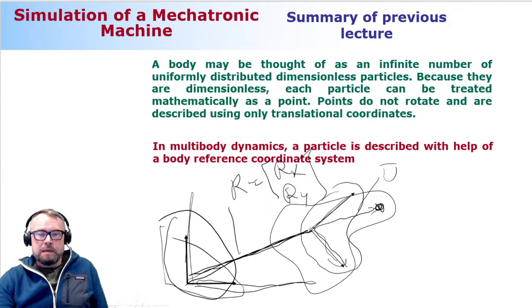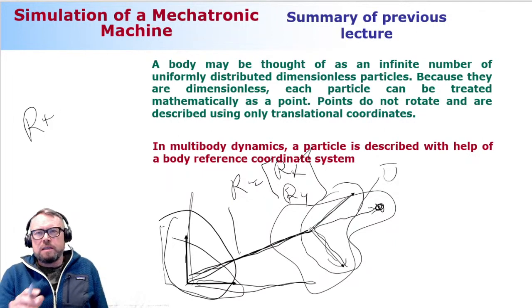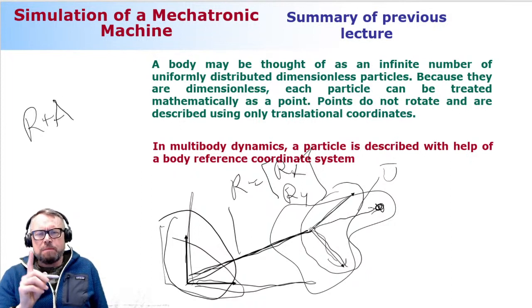All right. So then let's write this equation here. Then we need to take the orientation of the body reference coordinate system into account. That we can take into account by using a 2x2 rotation matrix that maps description from body reference coordinate system to global coordinate system.